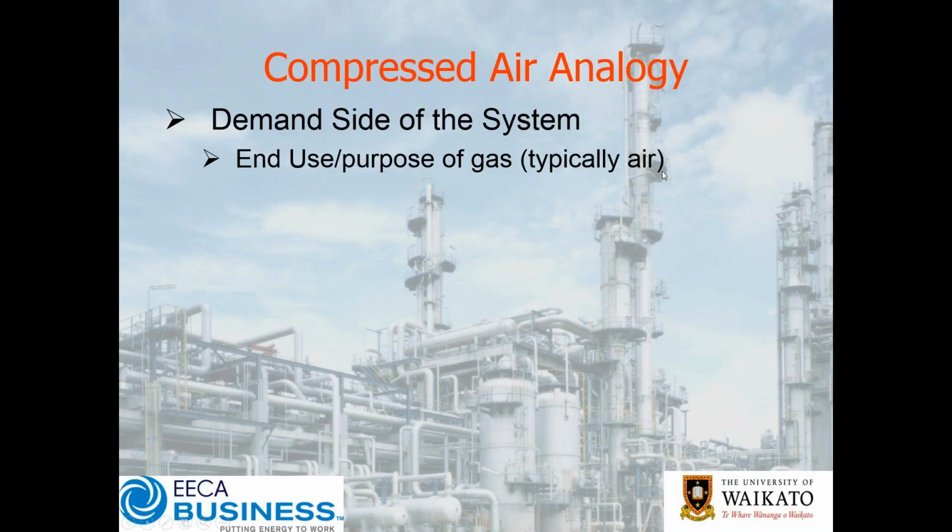If it's a dust extraction system, or it could be a process heating requirement where you're trying to dry something, the question is what are you wanting the air to do? So it'll be perhaps a certain air flow rate at a certain temperature, or it might be providing a certain suction to remove or convey a waste material away.